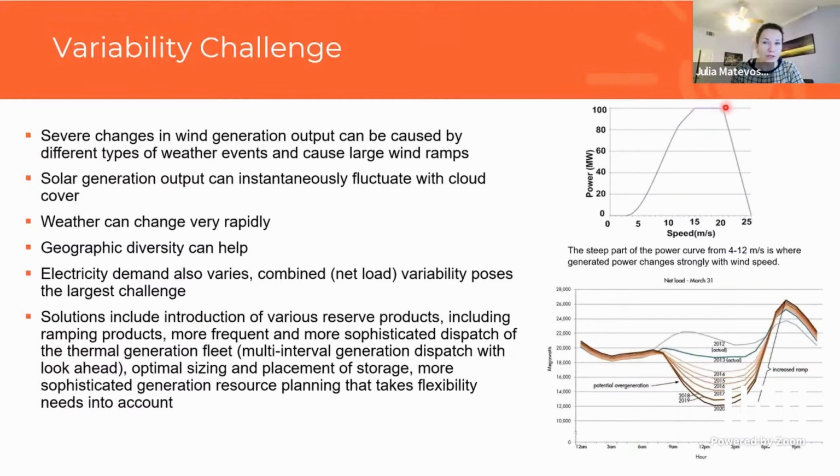And then as wind speed gets too high, the wind turbines pitch their blades to let this wind through and not overload the generator. And so this power is gradually decreased back to zero to protect the wind turbines. So you can see here that in this range, wind speed change doesn't do anything, but in these two ranges, there can be rapid variations with small variations in wind.